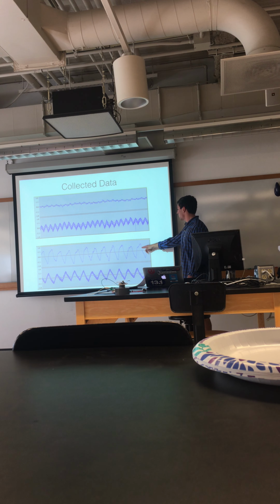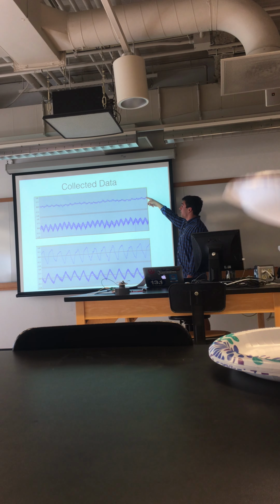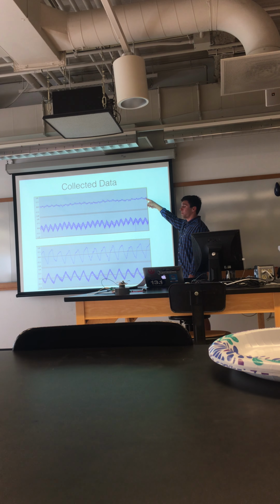This signal is a voltage swing from peak to peak, from upper peak to lower peak. Same for up here. The signal is much smaller. They've both been amplified by 15 decibels, so they're both on the same scale. But this signal is much, much smaller because it's picking up less infrared reflection off the clouds versus this signal where you're getting a lot more infrared detection.